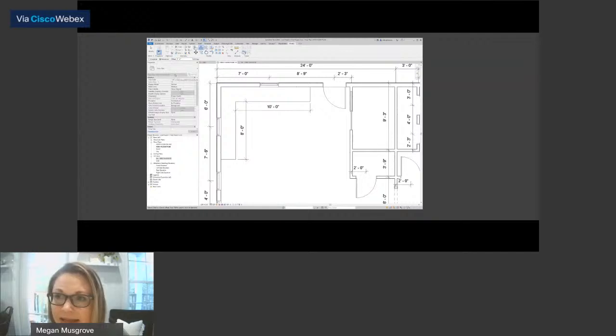So we're going to do OF, or you can hit the button. And I always leave this set to numerical. It's what it defaults to. I don't even know what graphical does. I would say forget it's there, but I never use it. So I use numerical. We're going to go in here into the offset, and this copy defaults to checked. You're going to leave that checked, and I'll show you why. So we're going to select that. It's wanting to do 4 inches. We are going to do 3.5 feet. So 3 space 6 enter.